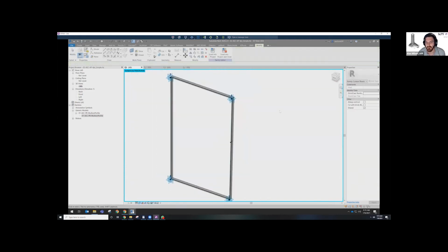And then I just click create form. Once you click create form, Revit understands that you have a rail and you have a profile, and it just automatically creates the sweep for you. From here, you can add your subcategories, add your materiality, things like that, any other additional parameters you need to add.